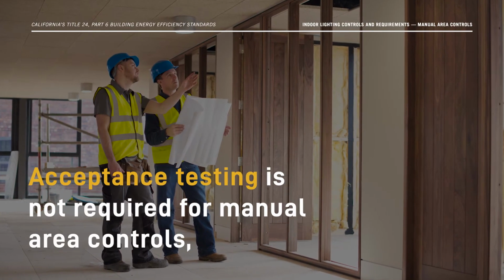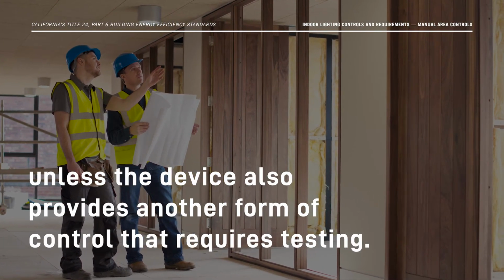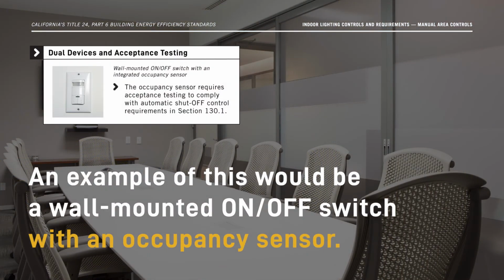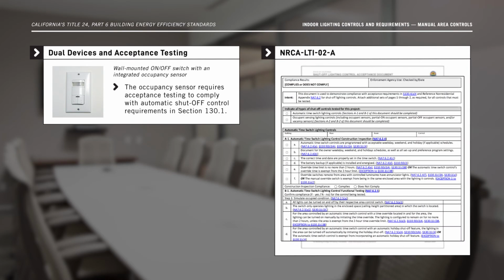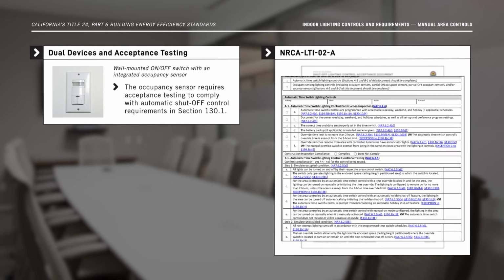Acceptance testing is not required for manual area controls unless the device also provides another form of control that requires testing. An example of this would be a wall-mounted on-off switch with an integrated occupancy sensor, as this device requires acceptance testing to ensure compliance with the automatic shut-off control requirements contained in Section 130.1c of the Energy Code. Test results for this device type are documented on Certificate of Acceptance Form NRCA-LTI-02-A.